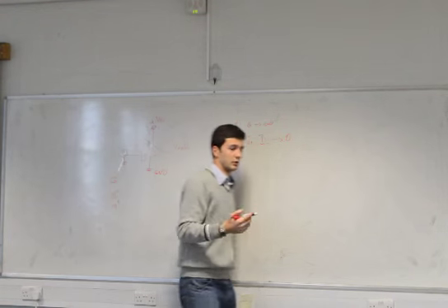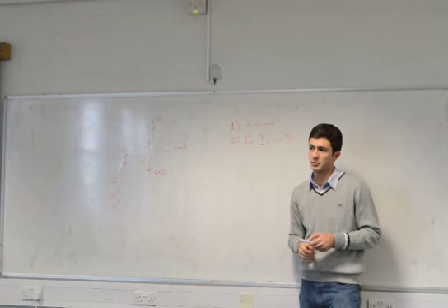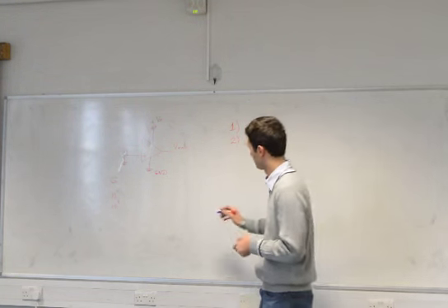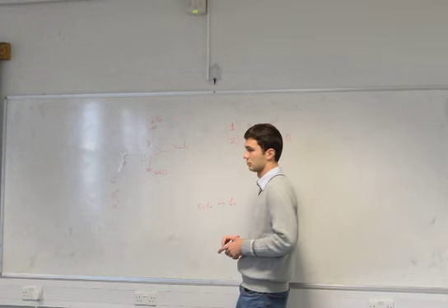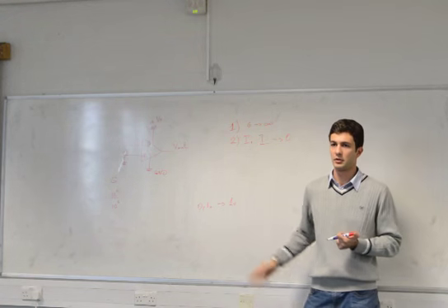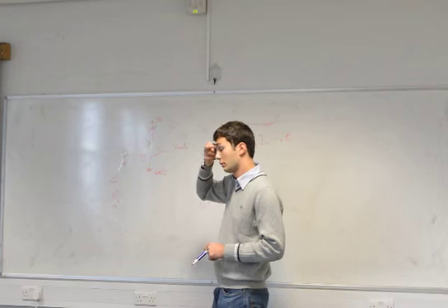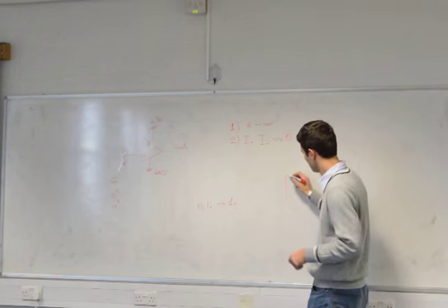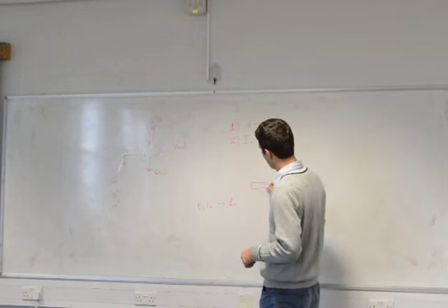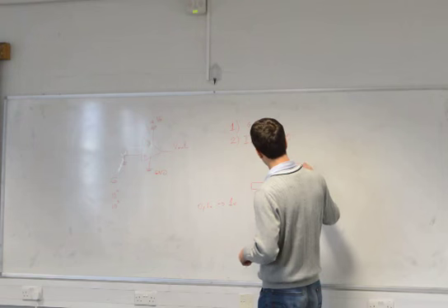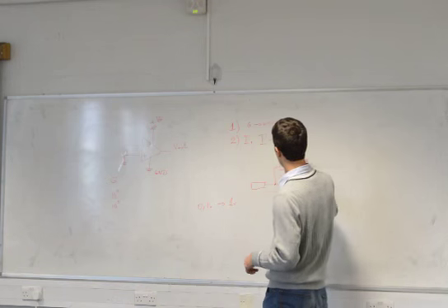Because we don't need the amplification to be infinite or very big. Yes, because, for example, we want to amplify 0.1 volts to be 1 volt, because our device doesn't sense this. What we do, we can define the gain. The gain is defined like this. You put a resistor here, you put another resistor here. This is R1, this is R2.